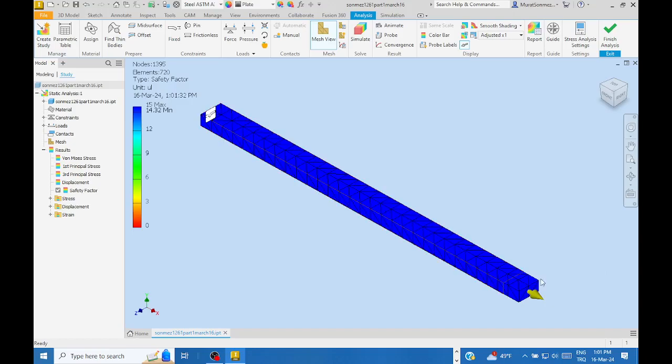And actually, if we solve this problem in Fusion, Fusion is more powerful and more friendly. Fusion will say that, yeah, you're wasting material. Okay, use the shape generator facility of the software and then decrease the material, which makes the object more sustainable, saves material, and also decreases its inertia.